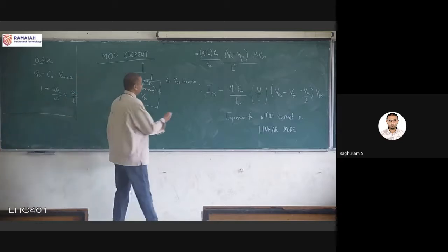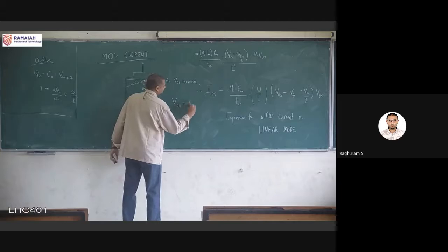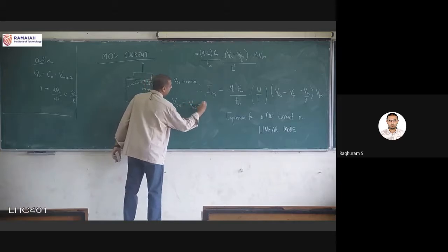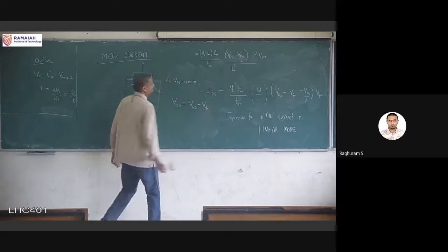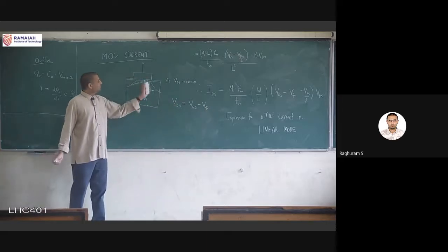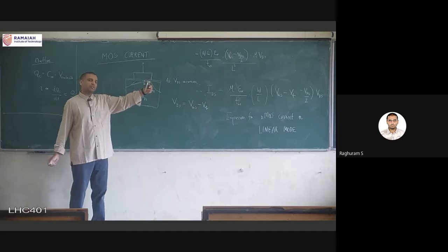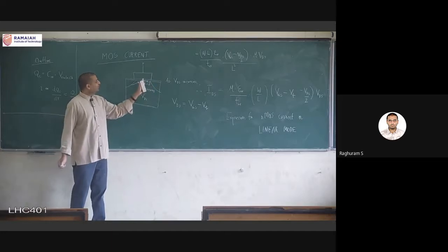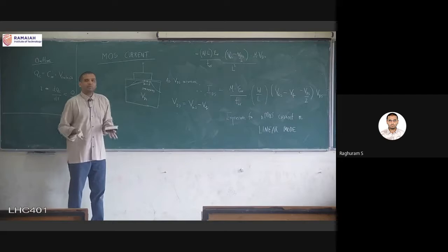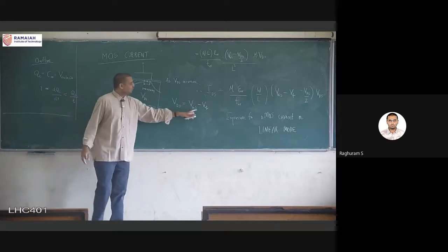That is given by the boundary condition where VDS is equal to VGS minus VT. This is the part of VGS which is responsible for the horizontal movement. As we go above from linear into saturation, all that additional VDS is only appearing in the pinch-off point where there are no electrons. The electrons have all been already attracted into the drain region. So that is why this is the boundary condition.